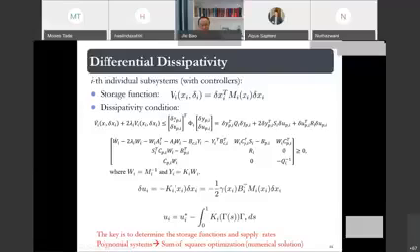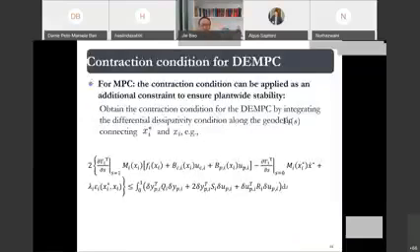And eventually we would have the control law, delta u as a function of delta x. And when we implement the actual control, the actual control is the integral of delta u along something called geodesics, which is a result of a parameterization of all the trajectories. I don't think I will have time to go into the details, but what we did was extend that result to model predictive control.